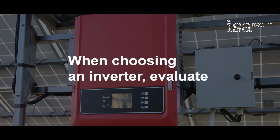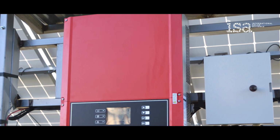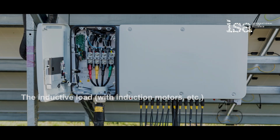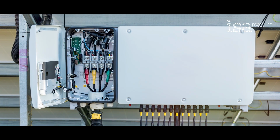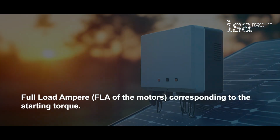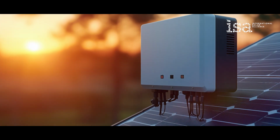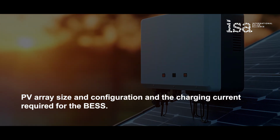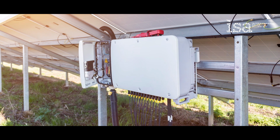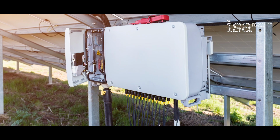When choosing an inverter, evaluate the AC peak power output required in the grid along with the type of load. The inductive load with induction motors, etc., has to be carefully considered while determining the inverter capacity, keeping in view the requirement of full load ampere, FLA, of the motors, corresponding to the starting torque. Grid frequency and MPPT capacity are to be determined based on the PV array size and configuration and the charging current required for the BESS. MPPT capacity to be suitable for the PV AC output power and grid frequency range.